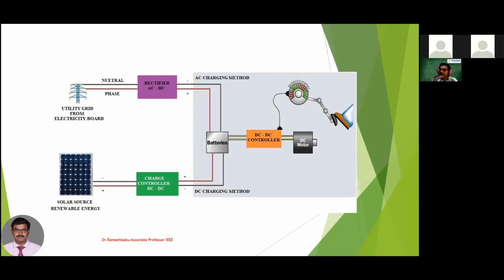Okay, and there is a controller. The battery provides a constant DC voltage, it never gives variable DC. That constant DC voltage may be converted into variable DC voltage with the help of the power converter. How much do you want to convert? Suppose from the battery I am getting 48 volt DC, and I want to convert it into 110 volt DC, to get a boost voltage.